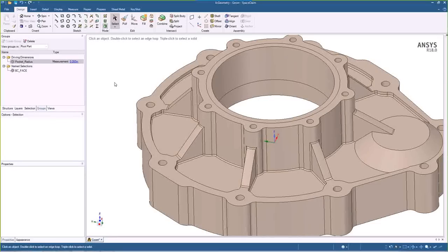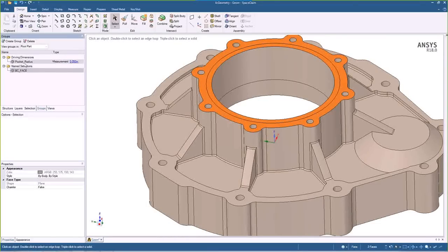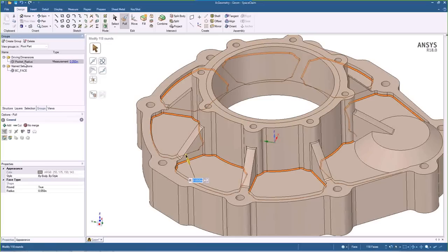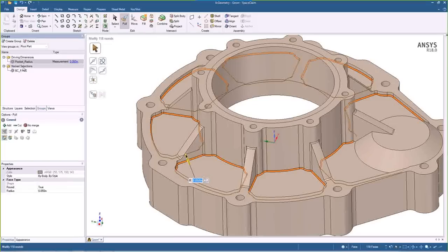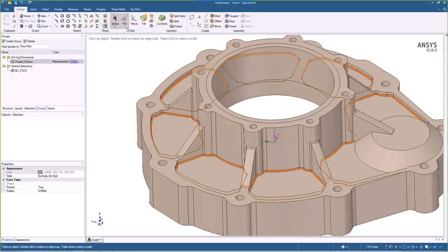So now that's the difference between having surfaces selected versus selecting the surface and then using a Pull or Move. So if we grabbed this parameter, go off the Move tool back to Select, create a group.